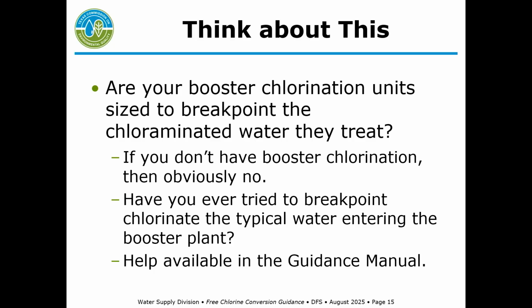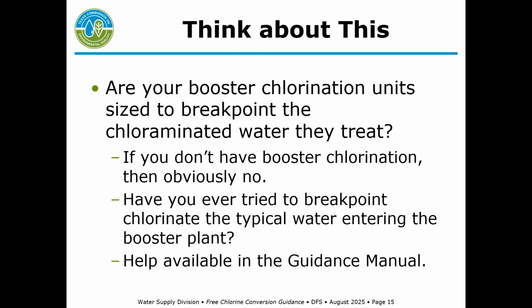So, are your booster chlorination units sized to breakpoint the chloraminated water they treat? So let's say you're a purchase system, you're buying chloraminated water from somebody, and you've got a booster station. If you don't have a booster station, obviously no, you can't breakpoint chlorinate the water. But have you ever tried to actually breakpoint chlorinate the water coming from your supplier?